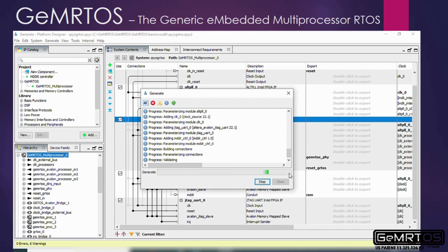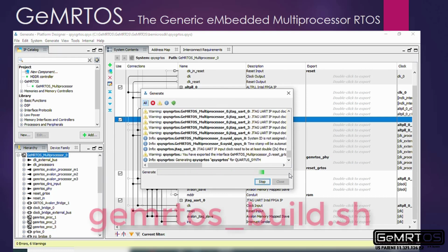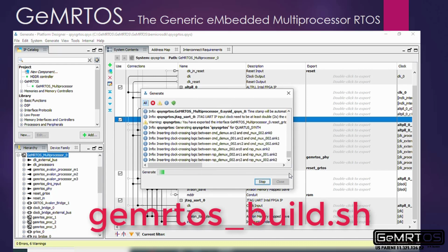To prepare for hardware compilation, the Platform Designer instantiation template must be instantiated in the Quartus Prime project. Once the Platform Designer component has been instantiated, the Quartus Prime project should be compiled. The software application can be designed using the Eclipse environment as it is for classical uniprocessor designs.